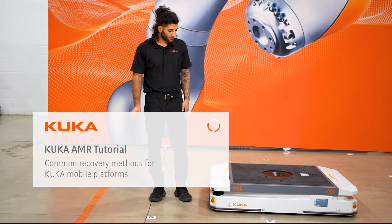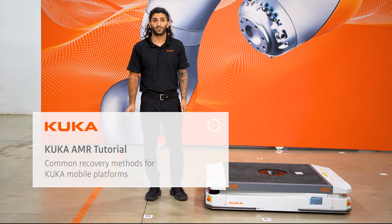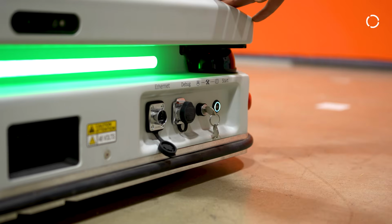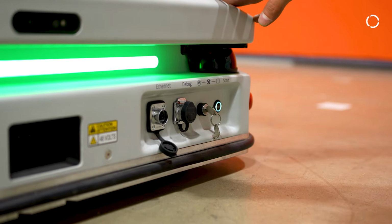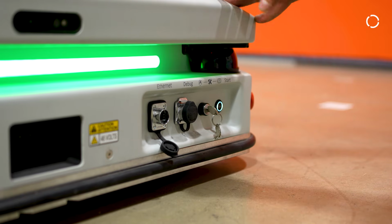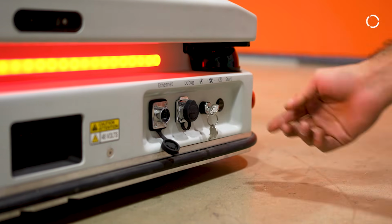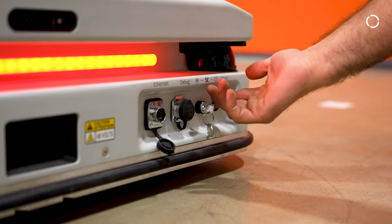In this video, we'll be going over the recovery modes for the AMRs. There are two methods of recovery for the AMR, brake release and QR codes. The first step in using the brake release method to recover the AMR is first to spin the key into the brake release mode and then hit the start button.